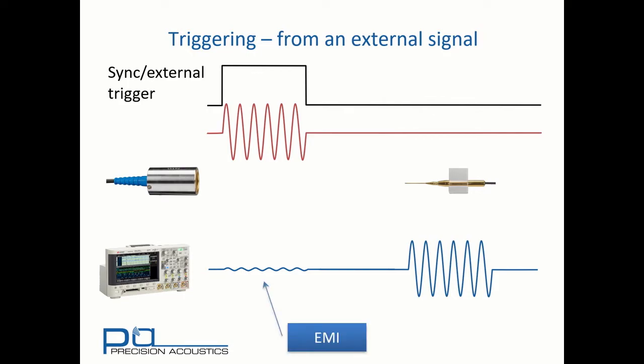We can clearly see there's a small trace at the same time as the transducer drive signal. This is electromagnetic breakthrough. This is entirely common with transducers, and because we're triggering acquisition from the point at which the transducer drive signal occurs, and this signal is travelling through the water at something close to 2 times 10 to the 8 meters a second, it apparently arrives instantaneously. Later on, we have our acoustic signal.